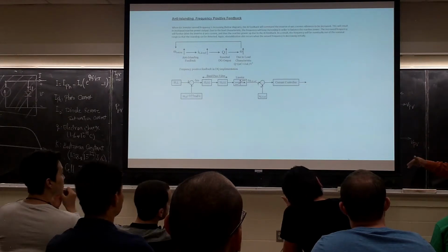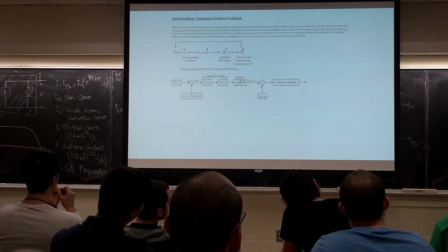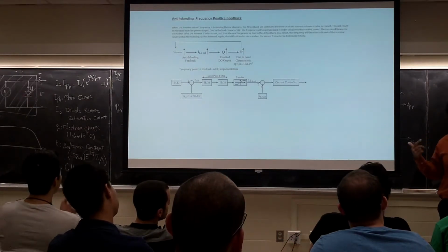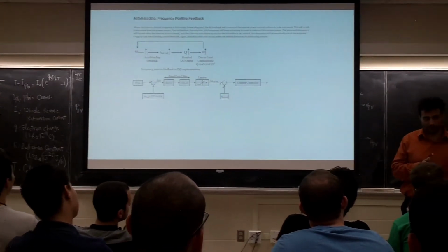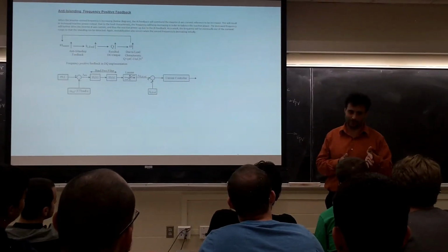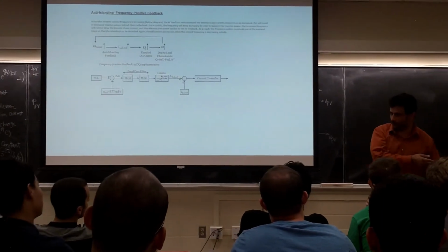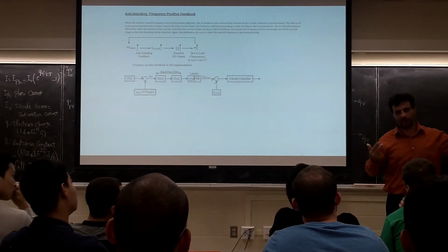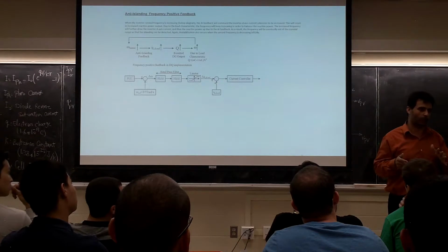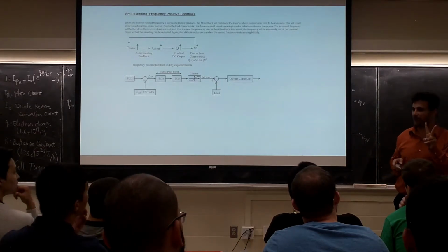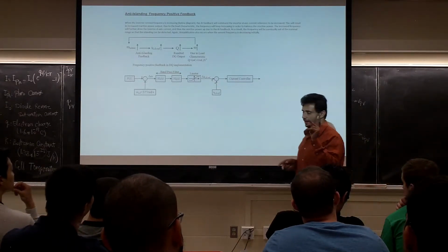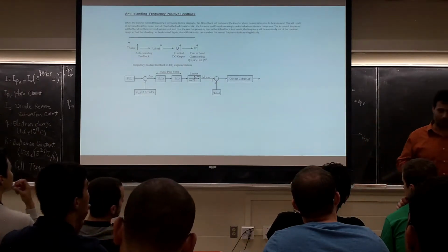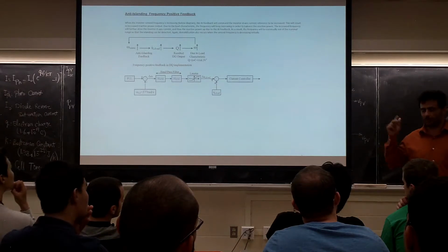As soon as the grid is gone, you can still generate power if you want, but you cannot be connected to the grid anymore. If you're going to generate for yourself, they call it standalone mode. But if the grid is there and you're connected to it, they call it grid-tied operation. There are two modes for every inverter: grid-tied and standalone operation. Most of the PVs now installed in homes don't have a standalone mode. As soon as the grid goes off, they shut down.